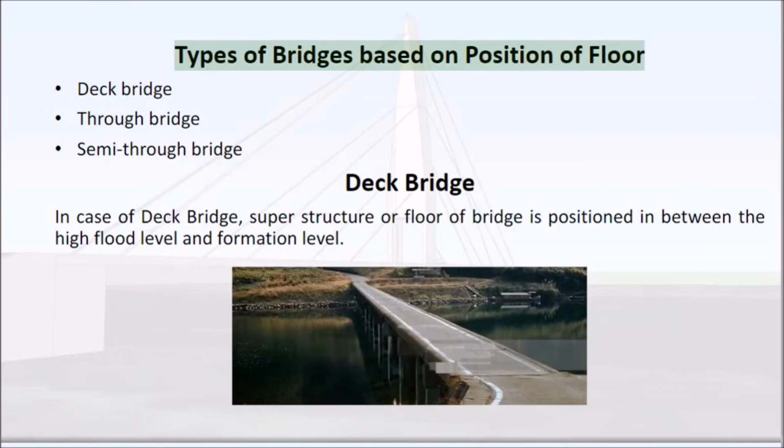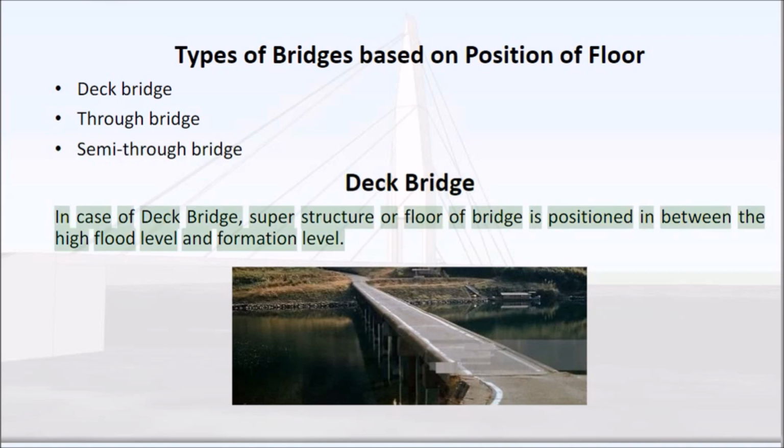Types of bridges based on position of floor: deck bridge, through bridge, and semi-through bridge. Deck bridge. In case of a deck bridge, the superstructure or floor of the bridge is positioned in between the high flood level and formation level.